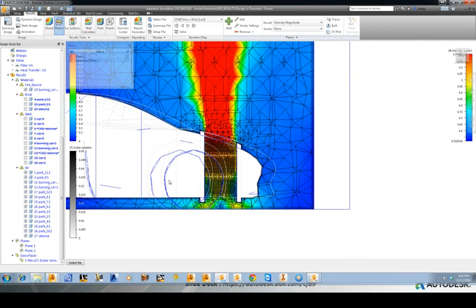Now, because there are such long run times, it ends up being a balancing game. You're not trying to get dead accurate results here. You're trying to get an understanding of smoke control, of where it's really flowing, and getting enough mesh to get a fairly qualitative view of what's going on is many times the goal with these kinds of analyses. So in this case, it does a very good job of allowing the hot plume to rise and then reach the outlets that are defining the model.